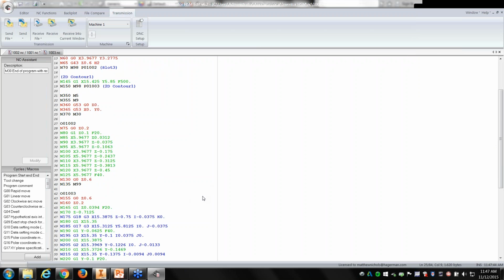For inputting tools from outside sources, the way that I have typically done it, because I've been working on creating some Mitsubishi tool libraries, so there's a way that you can do it. You can either create them individually inside of your tool library, or what I typically do is I'll create a few of them, export them out to a TSV file, and then you can pull that into Excel, and that'll give you all the basic columns that you need to fill out for all the tools. And then you can just start adding rows of tools to it.